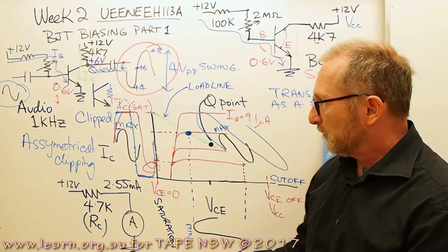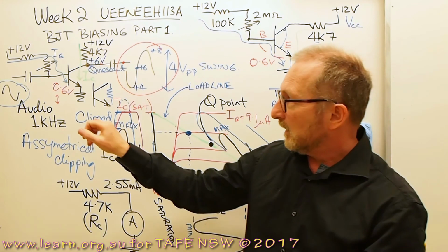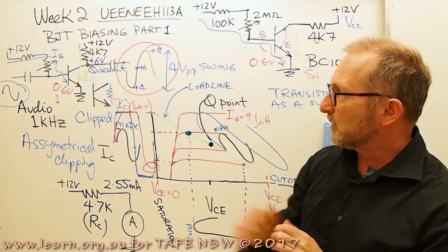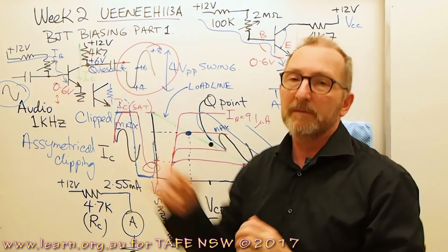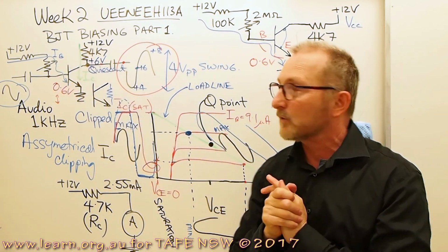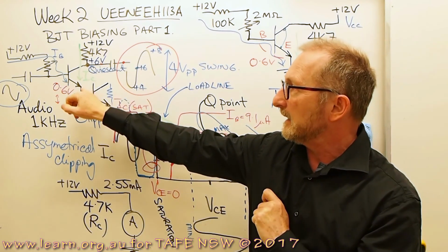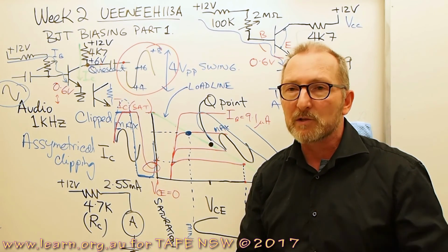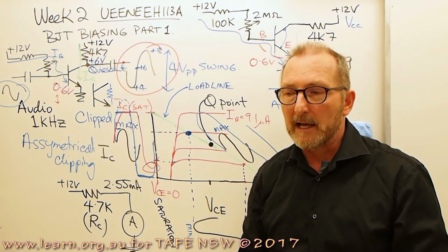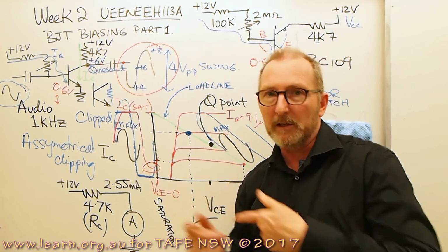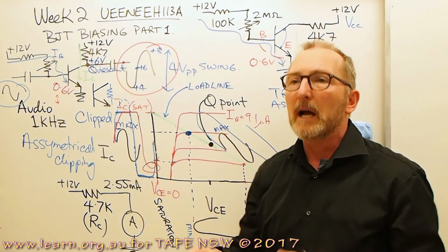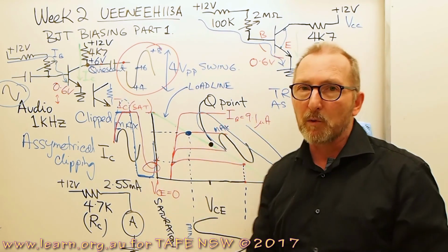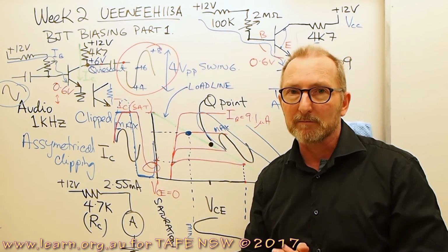And then with the audio, we're going to see a little bit of distortion because this type of setup is more configured for a transistor switch. For a transistor amplifier, it needed a little bit more resistance in the emitter circuit. So I'll demonstrate that with the oscilloscope as probably a part B to this video. So there'll be the theory part, part A, and then I'll do a part B, which is the actual lab with the board, showing you all those points about what I've talked about in this theory lesson.